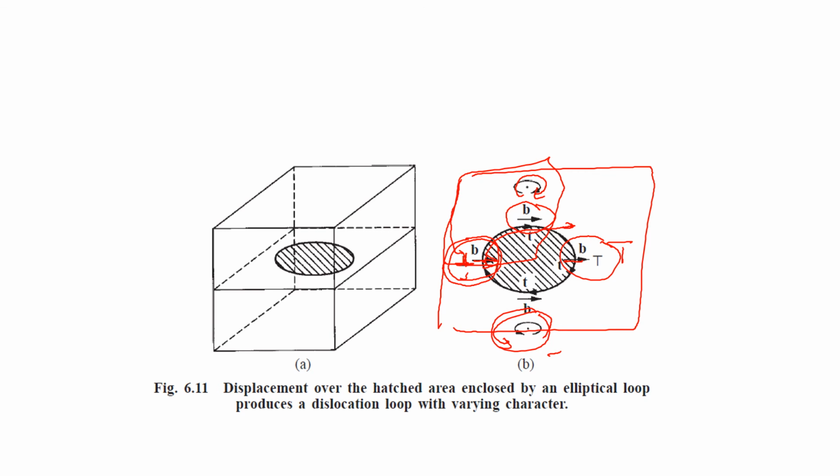Here the Burgers vector can be resolved into two directions, parallel and perpendicular to the line, and thereby define the screw and edge components of the combination here. You know, dislocations have certain geometrical characteristics. The vector sum of Burgers vectors of dislocations meeting at a point, that point is called a node, must be 0.